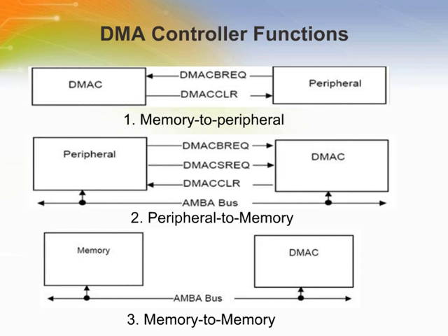Memory to memory. The start condition for this type is that the channel commences transfers without DMA requests. And the stop condition for this type is when all transfer data has finished transferring, then disable the DMAC channel. Peripheral to peripheral uses burst request and single request.